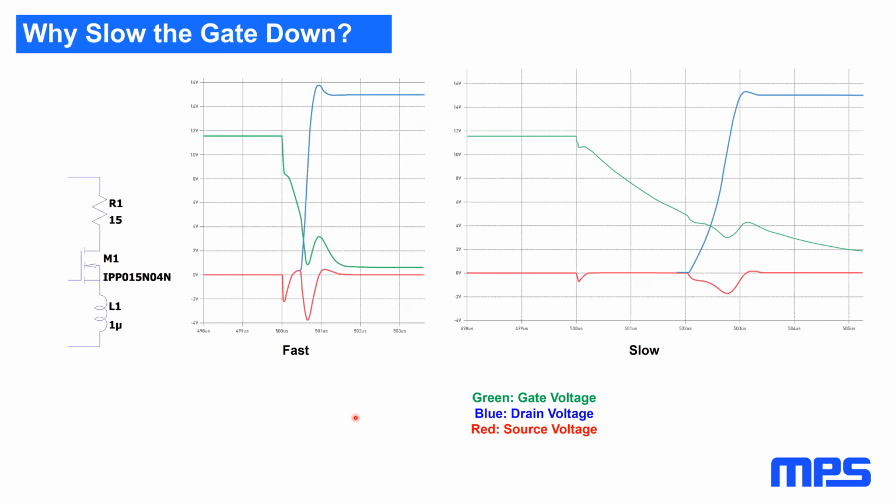I mean, MOSFET SOAs are fairly forgiving in general, so I have not had to worry about that. It would only become a factor if you're switching quite slowly and at relatively high power levels. It's an interesting question. It may affect your choice on how fast to switch the gate more than anything.